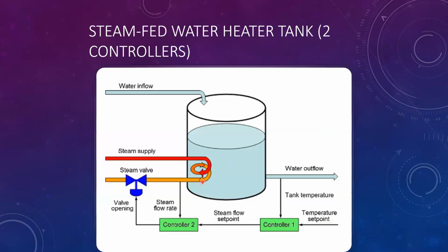The advantage is that this system can provide a faster compensation when the steam flow is disturbed, as a single loop would let the temperature drop before the sensor could notice. So having a second sensor, the flow rate can be maintained quicker and more precisely, as whatever steam flow rate it desires, it will get.